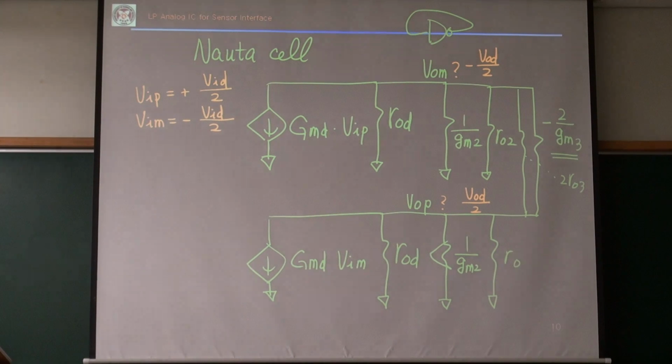Those are the only driving current, right? And then what's the resistance between this node and that node? So eliminate the current sources, then you can see this impedance. I can redraw this part: this current is the same as that current.